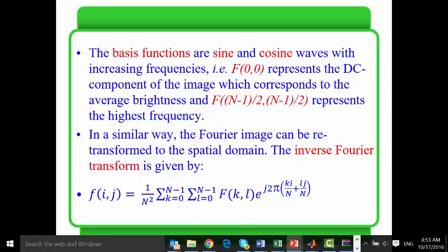components. Okay? Here also, we have said that this kind of transformation is bidirectional. So as we have the transformation from the spatial to the frequency, I have as well from the frequency to the spatial by using this inverse Fourier transform. Okay? It has almost the same expression, except here instead of e to the power minus j, I have e to the power plus j.